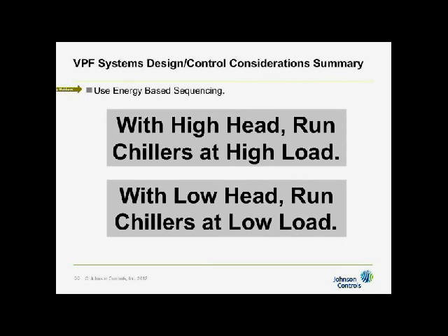When you're at high head, remember to run your chillers at high load, which is load-based type sequencing. When you're at low head, you want to run at low load, which means you want to run 2 chillers to do a 1 chiller job. You want to run 2 pumps to do a 1 pump job, etc. Typically, not always. It depends upon where you are in the pump curve and where the efficiencies lie, but typically you want to run multiple units here and you want to run single units here. Okay?